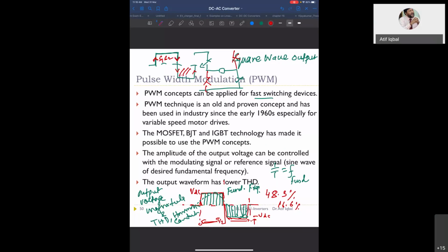So this is equal to the fundamental switching frequency. The switching frequency means at what frequency it switches, and it is the same as your fundamental frequency: one on and one off in a whole period. So you have very low switching losses, because the switching frequency is only 50 hertz. But when you use the PWM technique, you switch many times. It can be 5 kilohertz or 10 kilohertz switching, and now with new devices, silicon carbide and gallium nitride, we can have 100 kilohertz, 150 kilohertz, even 200 kilohertz switching. So very fast switching you can do.